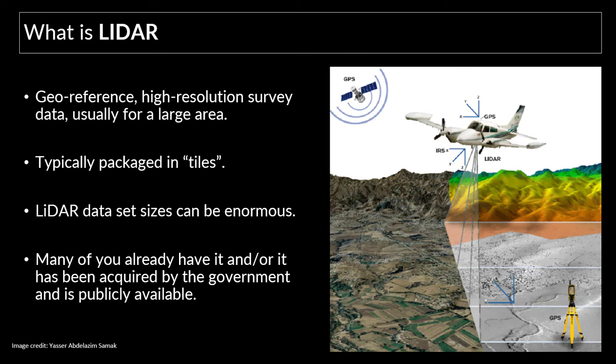So when you're bringing in huge data sets, you need to be able to, first of all, choose where the data comes from, so you don't bring in data outside your area of interest. And then you may need to thin it down to make the data set manageable. LiDAR is generally created from an airborne platform, a plane, a helicopter, sometimes drones. And the data accuracy is on the order of about a decimeter, 10 centimeters, a few inches, plus or minus, in both the X, Y, and the Z dimension.